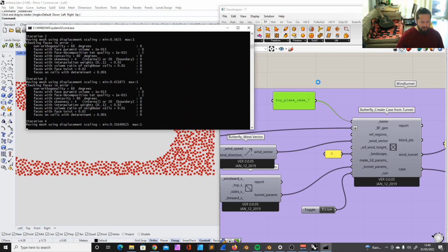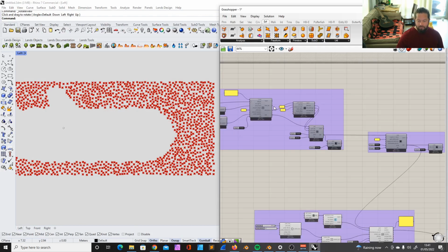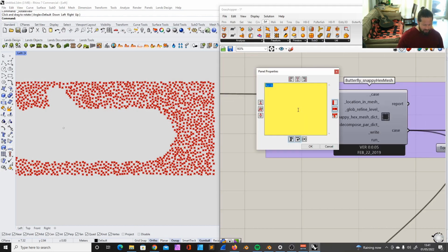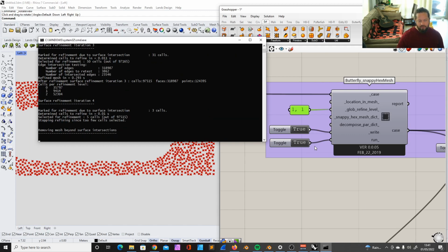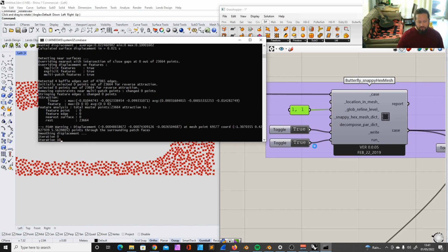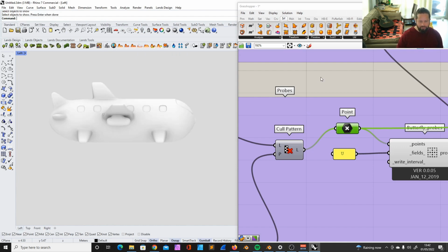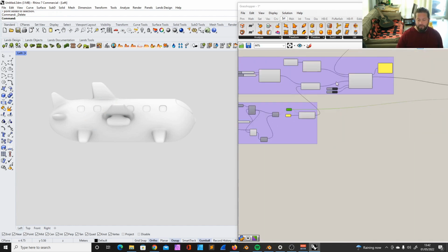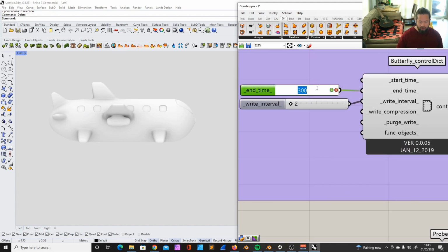So I'm recreating the hex mesh and the block mesh, and I think maybe this time we crank it up a bit, just to make it a bit more accurate. So we might see also difference here. Let's do this. Takes a bit longer, but here in the video you don't need to wait because I just cut it out. Turning on the plane because it's nicer. I cannot get rid of this point, by the way. And now final rerun, write and rerun. We maybe add a bit more here, 500.